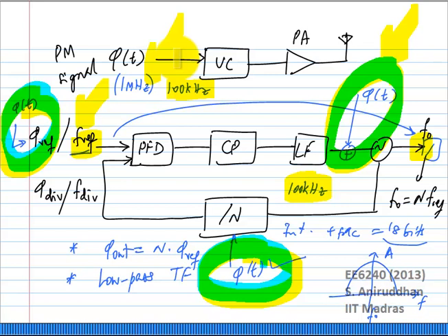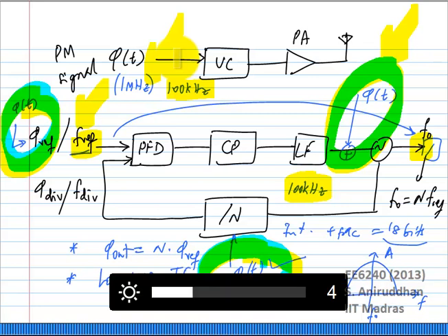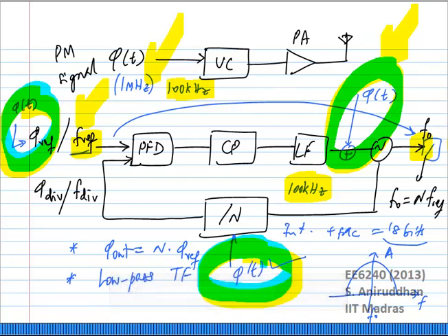We started off with GSM, but after that we have something called Edge, which is supposedly the next version of GSM, where apart from phase modulation, we also tacked on amplitude modulation. And now, of course, WCDMA and LTE signals actually have information in both the amplitude and the phase. It is not a purely phase modulated signal. Okay, it is more of a quadrature amplitude modulation, QAM kind of scheme that is used in these kinds of signals.